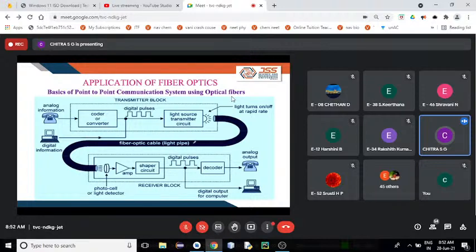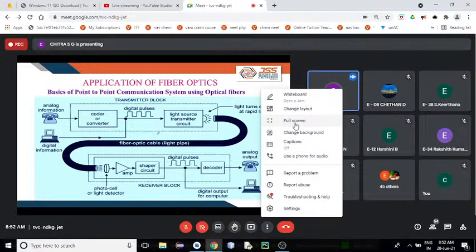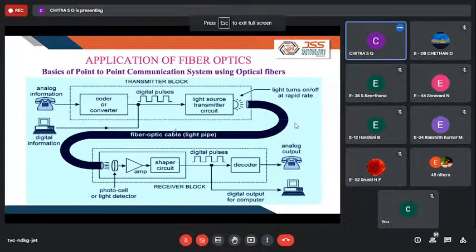So there we need an optical repeater in between. In this block diagram we have not shown it. The optical repeater will consist of a transmitting and a receiving section, where you have to modulate that signal, and once again you have to recast it, and then it will be fed to the optical fiber. On the receiving end we can see the optical signal will be fed to a photodetector.